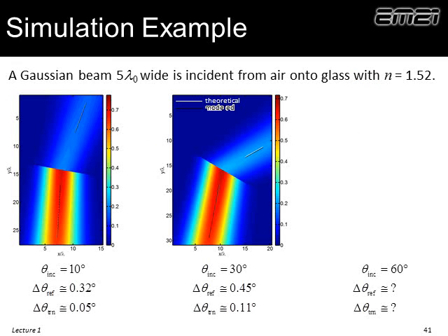So here are some simulations, and what I'm not showing in this figure is we have a normally incident beam coming down here, and it hits this surface, which is at an angle, and what you see is the reflected, and on this side is what gets transmitted. Now, how am I hiding that incident beam? Remember last semester our total field scatter field? I made this entire region the scattered field quantity so we don't actually see the source. There's a couple of little grid cells right along this surface where if we zoomed in we could see it, but instead we see the transmitted wave real clearly and the reflected wave. But we're coming in at normal incidence, and there's a black and white line here, and I forget which one's which.